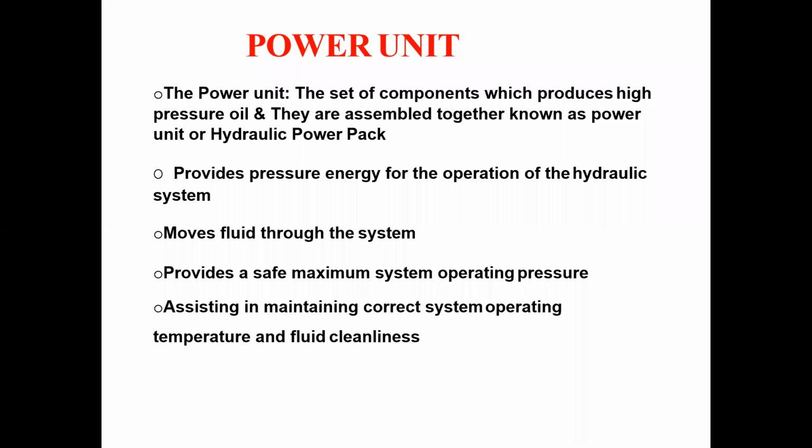Hydraulic power packs are readily available in the market. One can have it as per his choice. They have no need to purchase the components and to assemble them. A hydraulic power pack basically consists of oil reservoir, hydraulic pump with electric motor, pressure relief valve, delivery pressure gauge, manifolds with pipe connection. Manifold means multiple connections are provided here.